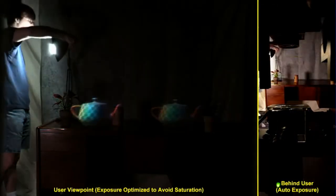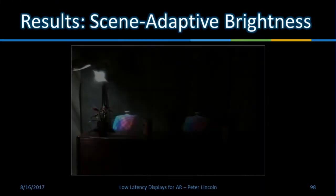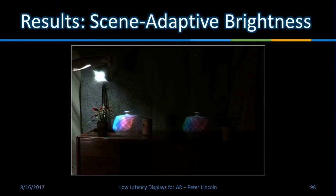What was the resolution on your light sensor? There were 4 in the lateral resolution. There were 4 sensors. Each is a 1 value sensor. They each give an ambient light value as measured. So 4 just laterally. 4 lateral horizontal sensors, and that was partly because we hadn't found an HDR camera that we would like to be able to put in that particular spot for it to get a more per pixel basis. So instead we were just interpolating it. And each light sensor is basically physically limited as to what it can see with the baffle.